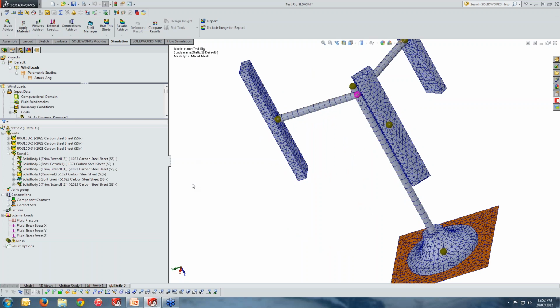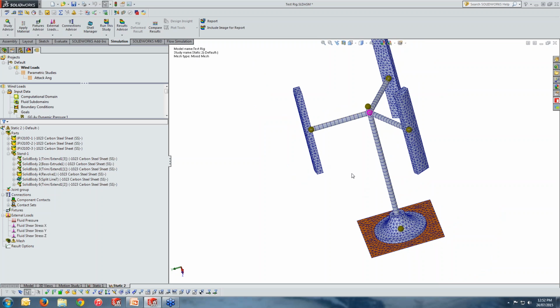That is something very important. If you don't, then the bonded contact between these two types of elements is either not getting established, or you might create a hinge connection and this can simply rotate against the beam element. That is something that needs to be done in order to complete the process.